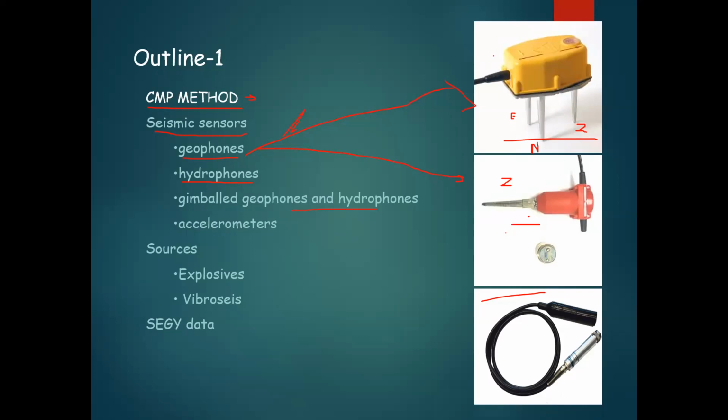Okay, so 12 geophones will be connected through the wire, but there are independent geophones also. Generally, the 3-component geophones are independent, meaning there is no wire connected to them. There will be one GPS attached to this, to record the coordinate or the position of the geophone planted. Similarly, there can be individual independent single component geophones as well.